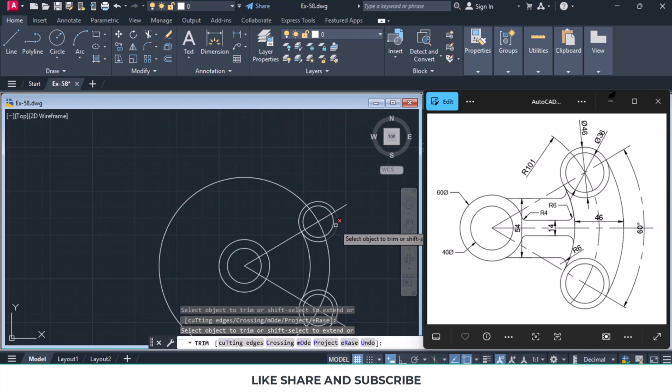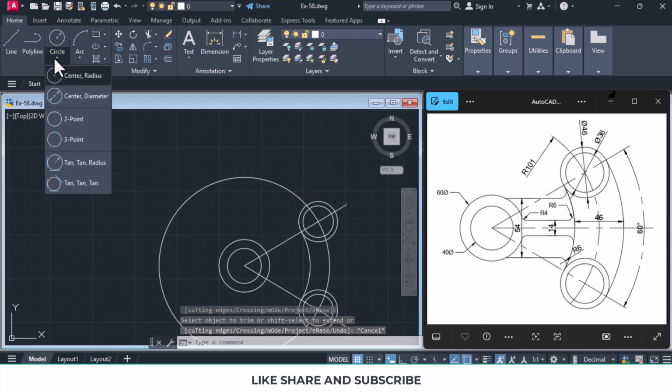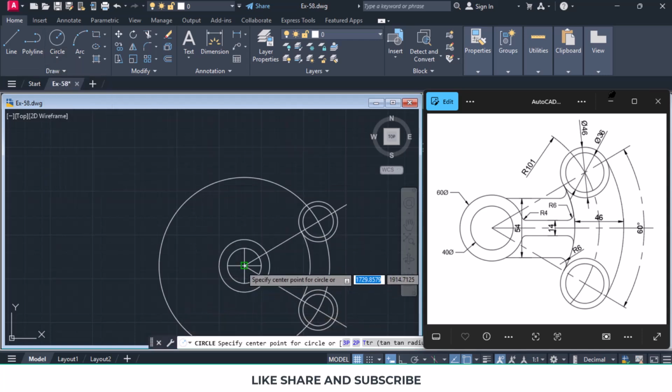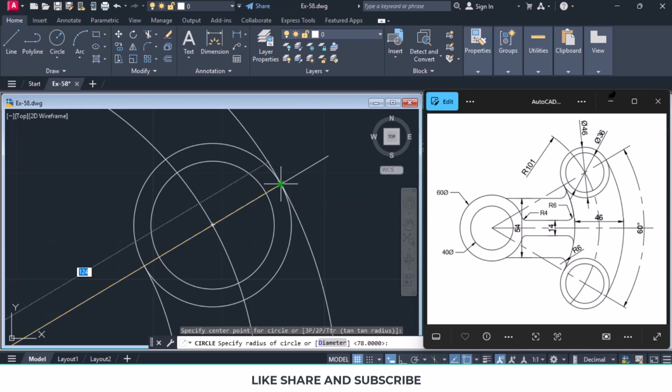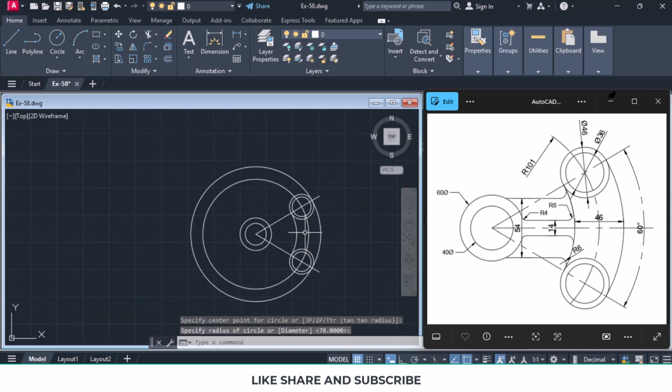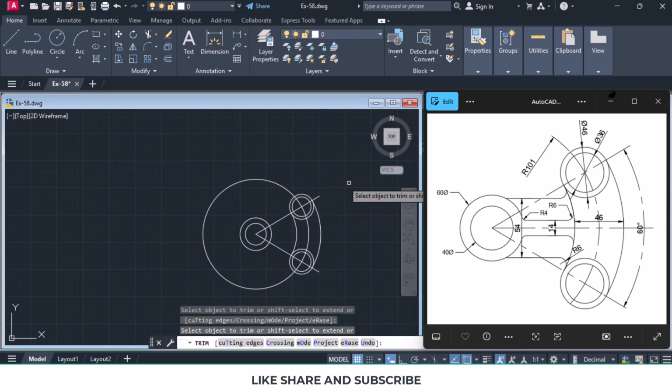In the same way, we want to draw the outer arc as well. So circle, center radius, this is the center point, and intersection of this is the radius, and the outer arc is ready. We'll type TR for trim and trim the unwanted part. So this arc is also ready. Press enter to come out of the trim command.